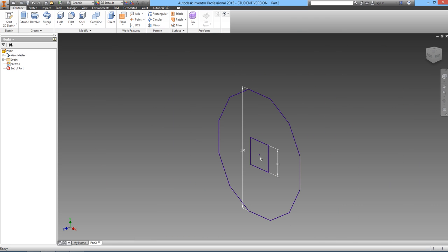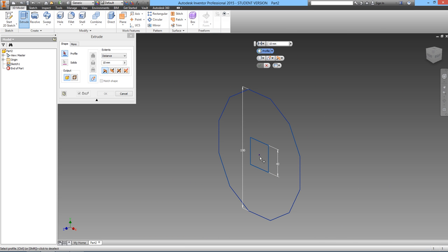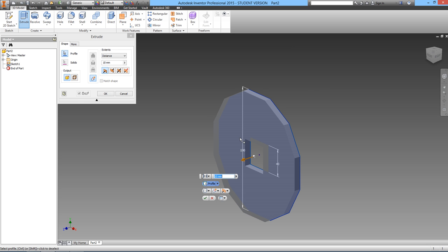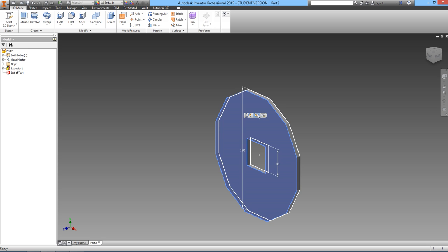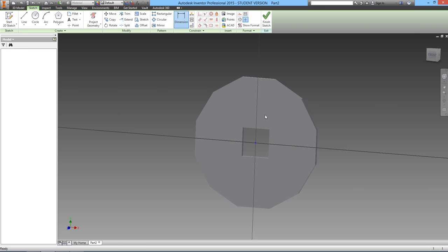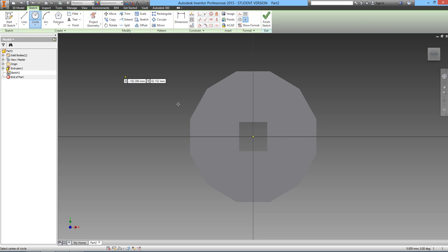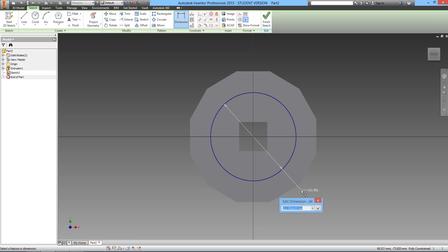And now I'm going to extrude the thickness, which is, in this case, 6. So I'll select my profile, 6, and hit enter. Now I need to locate my holes, and I'm just going to locate one hole for right now. So I'll left click on the face, and I'll click on my sketch tool. I'm going to draw a circle representing the bolt hole circle of my object, and put a dimension on this of 120.